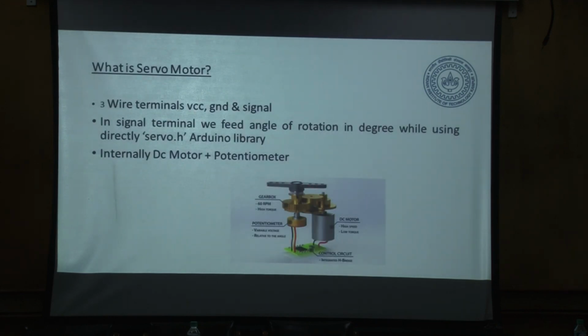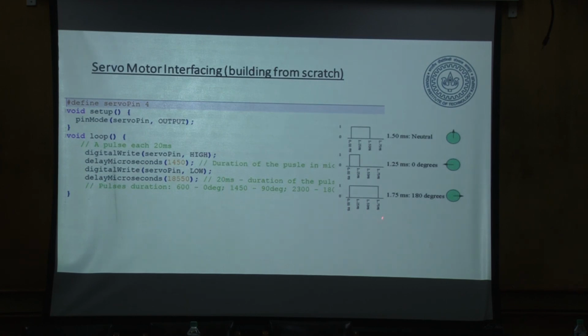Okay. So what it basically means is that if you give a duty cycle this much, then it will go and stop there. If you give 0 degrees, it's on the other side, so 0 to 180 degrees, and you can control any point in between wherever you want it to stop. Accuracy is not bad; it's quite good. It's about 0.2, 0.3 degrees.